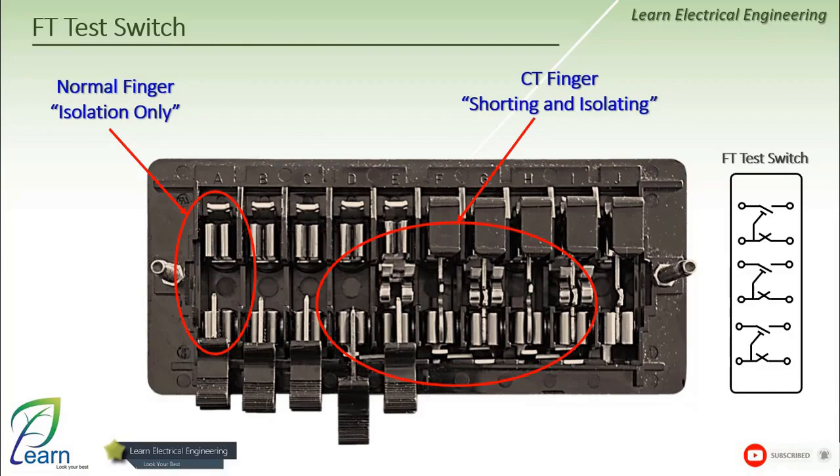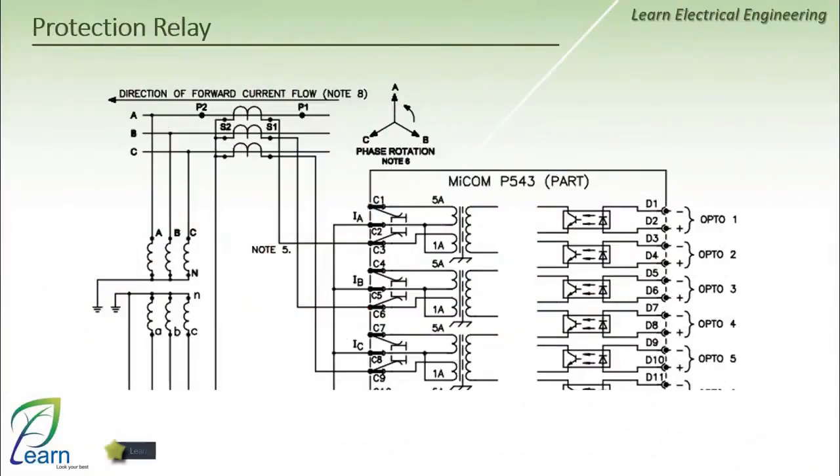The last thing we have is the protection relay or protection stages. We talked about the protection relay in the lecture on protective system elements, and among its components are analog inputs, which refer to CT input and VT input. Usually the CT input in protection stages is 1A or 5A, depending on the order number you purchase the protection stages with, and of course this depends on the CT you will use, according to the application you are using.